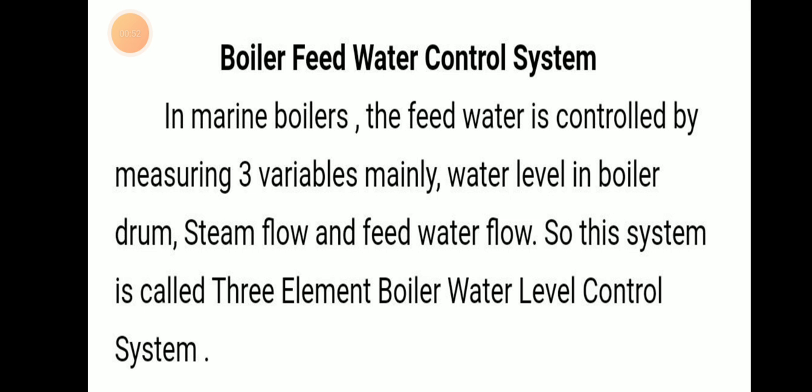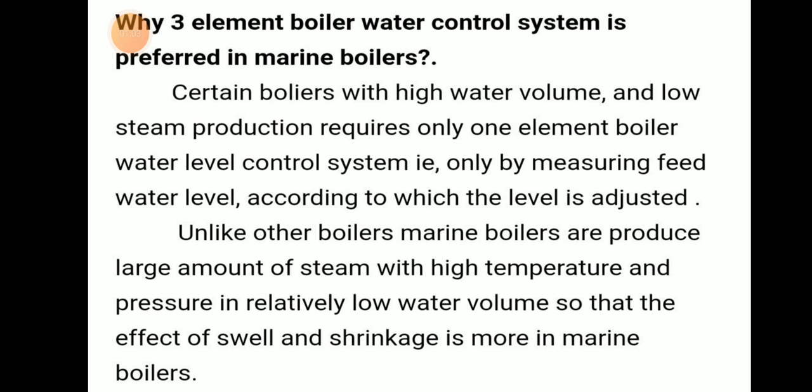So in marine boilers, feed water is controlled by 3 variables: water level in the boiler drum, steam flow, and feed water flow. This system is called the 3 element boiler water level control system. Why is the 3 element boiler water level control system preferred in marine boilers?